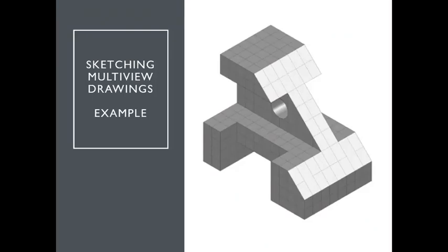In this exercise, we'll sketch a multi-view drawing of this object on paper. The size of the object is represented by the grids on the surface of the body. It'll be convenient if a square grid paper is used and we match the number of grids.